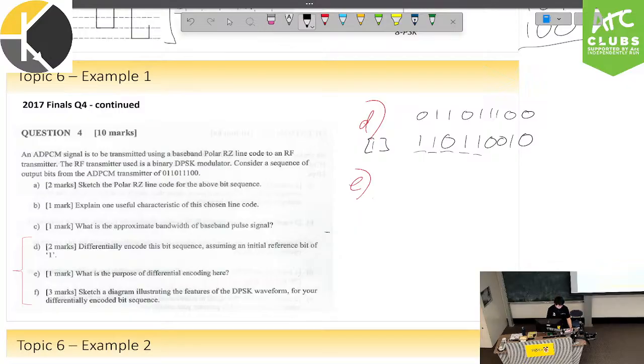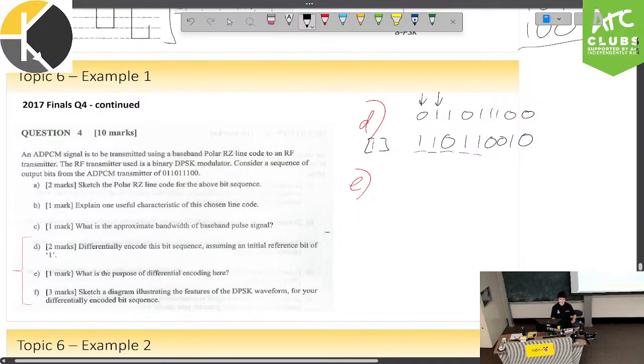So we can understand that, okay, a 0 might have a certain phase associated to it. A 1 might have a certain phase associated to it, just in modulation. However, when we encode it differentially, we can say, okay, did the phase change? If it did, then I'm going to apply it to my new system and I know what's happening there. There are no bonus bits of information floating. It's all dependent on whatever my reference bit is. So that way I keep rather consistent in my measurements. Going all right? All right.